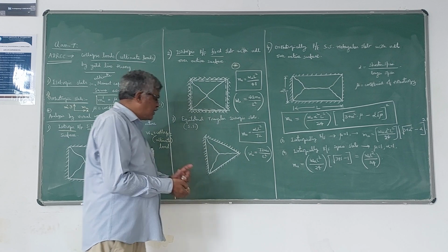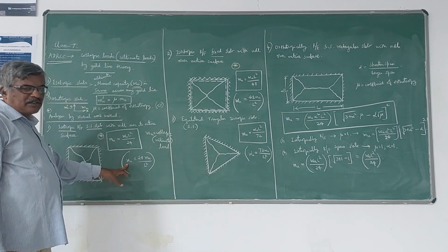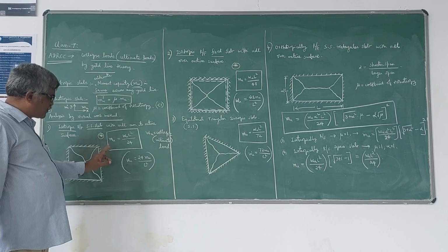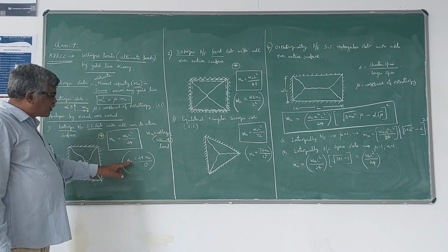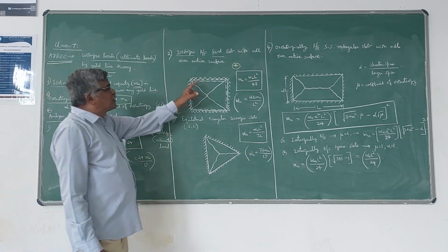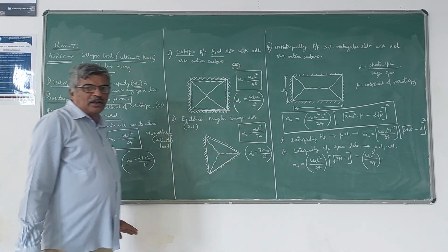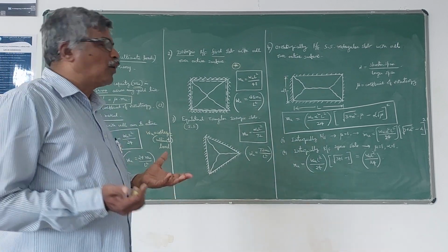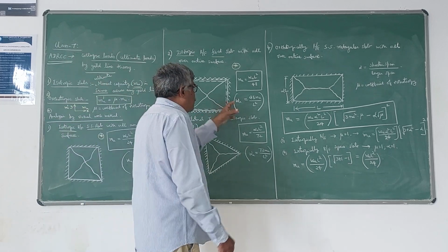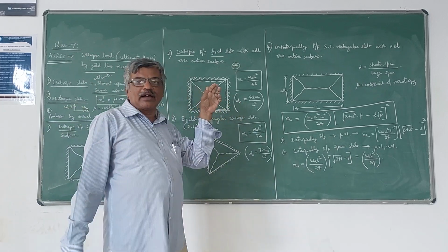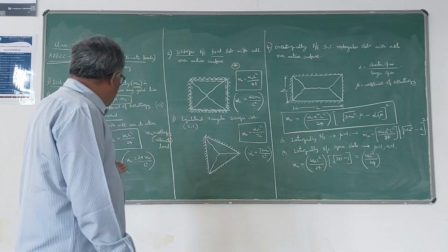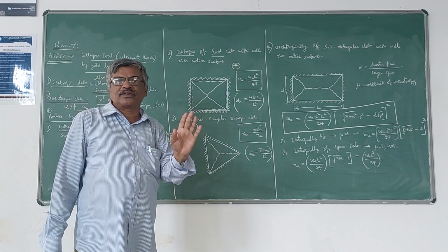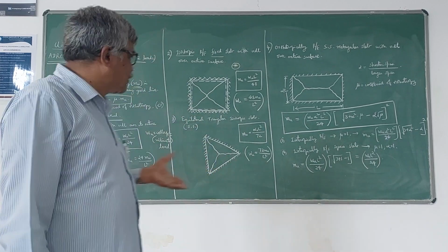If you observe this, here, if it is a simply supported isotropically reinforced slab, then your W is 24 into mu by L square, whereas if it is fixed, it is 48 into this. That means it is almost double. So a fixed slab can carry more load, or in other words, the collapse load of a fixed slab is double that of the simply supported slab. That is the meaning of that. So fixed slabs are stiffer than simply supported slabs.